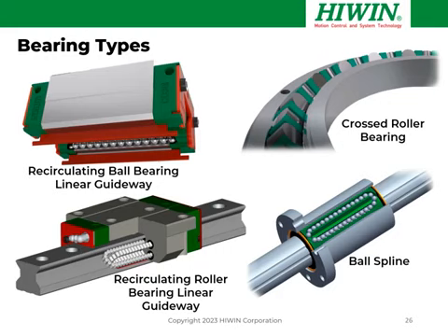Another type, perhaps the best overall choice for many applications, is the recirculating linear guideway bearing. There are many configurations and different options available that make choosing an optimal linear guideway bearing an easy decision in many cases. The linear recirculating ball bearing guideway has a bearing block that rides on a precision guideway. It can be either with ball bearings or, for heavier load capacity, roller bearing versions are also available. They can have very long lengths. The guideways can be joined together to essentially unlimited travel length, and they provide excellent load capacity.